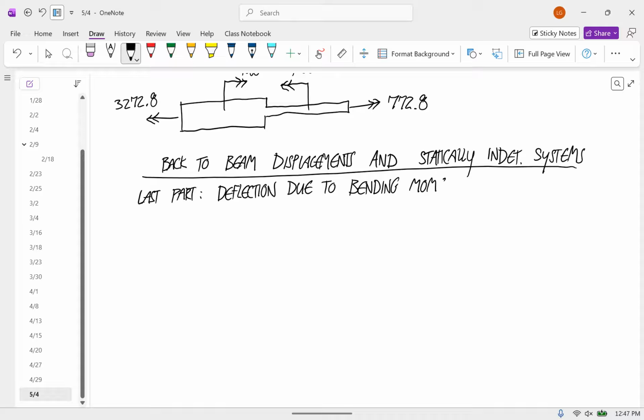I mentioned this last time, but I'll mention it again. I mean, you might think like, wait, we skipped shear force. Why we jumped straight to bending moment and then that's the last one? What about changes in shape due to shear force? Well, you're going to see that this is a differential equations approach that we use, and because of the derivative relationship between shear force and bending moment, these two are combined into one thing. So it's not like shear force isn't there, but we just don't need it. Bending moment gives us everything we need.